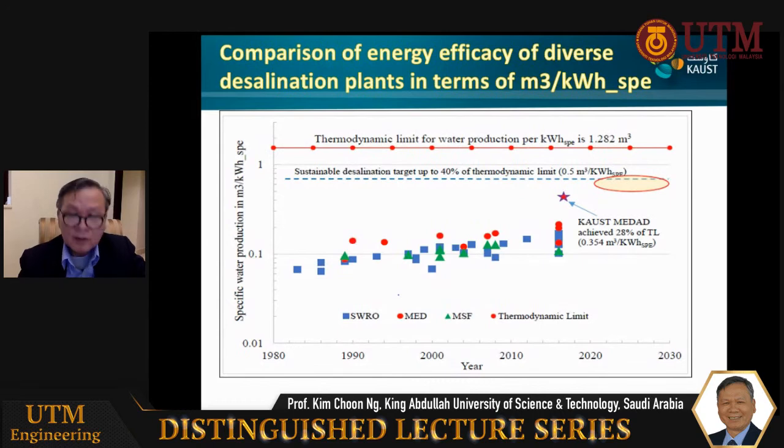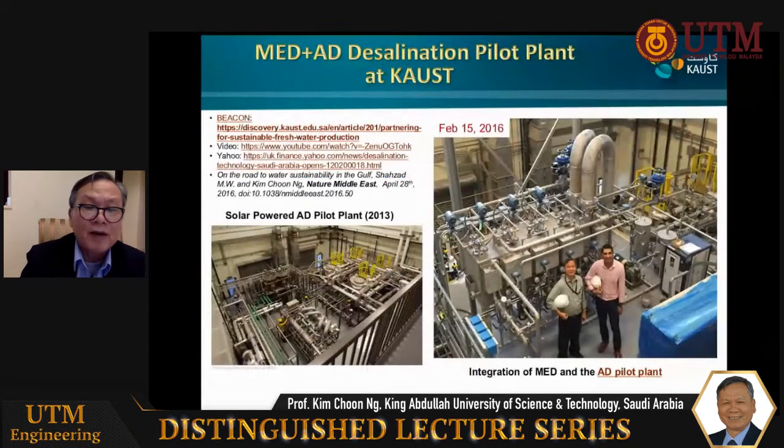So at COWS, we work on hybrid thermal desalination. That means we combine the proven MED with another thermally driven absorption desalination cycle. We call it MED plus AD, or MEDAD in short. In the laboratory, we have tested that this hybrid desalination can achieve 0.354 meter cube per kilowatt hour of standard primary energy. And the next slide shows our experimental pilots in COWS.